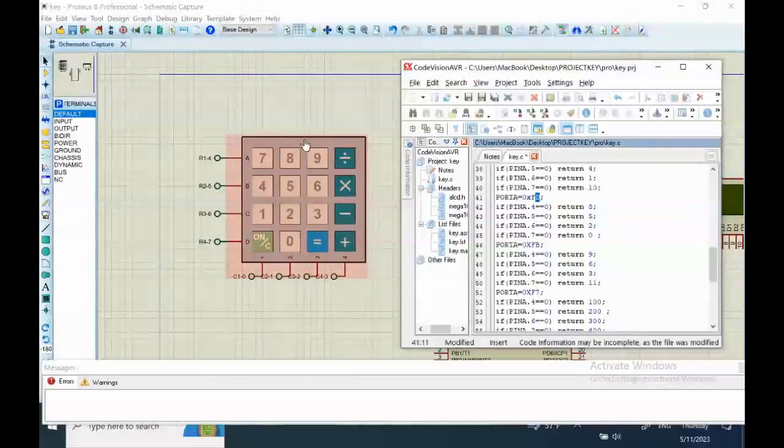About the other step, where I'm making column 3 equal 0, this code, okay? You see that for pin A bit 7, which is related to this key, the equal key, I used the number 11 because we don't have 11 here. You can use any other number, for example, 22, 20, 80, 100, 200, 400, any number which does not exist in your keypad.